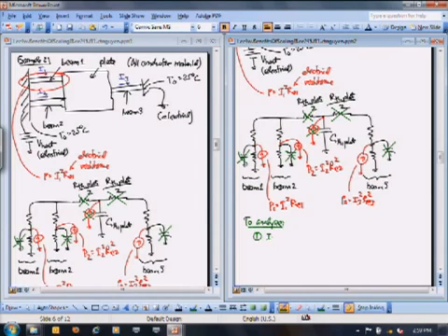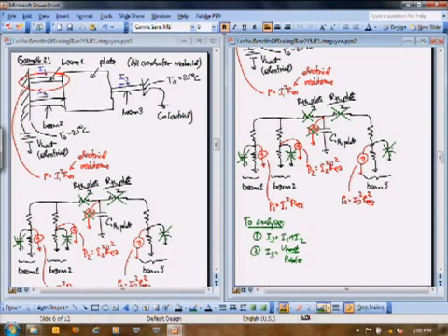You know that the current I3, what's that going to be equal to? It's going to be the voltage that I put across this whole thing. There's only one current going through this whole thing, and that's I3 in the end. So I3 is going to be whatever voltage I put across this, which I called V heat, divided by the total electrical resistance. I guess I should, in my nomenclature, do this. That's then going to be the current going through this.